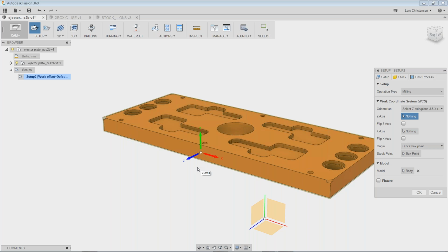If there's a 50-50 chance, it will not be in the right direction. That's exactly what we have here. So we're going to have to change this. What I want to do is switch this Z-axis to be where the Y-axis is right now, right? I need to rotate that because my machine, you know, I'm not going to machine this face here. I'm going to machine this face here.